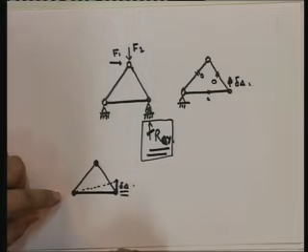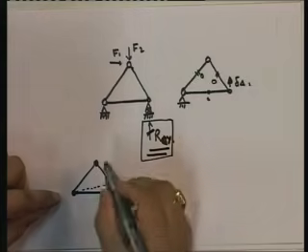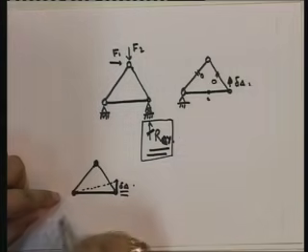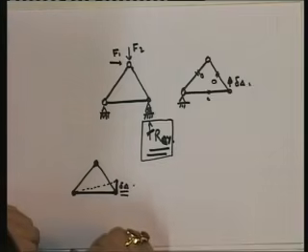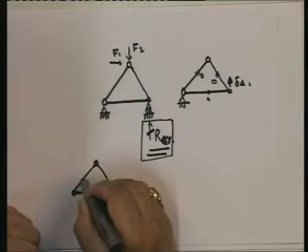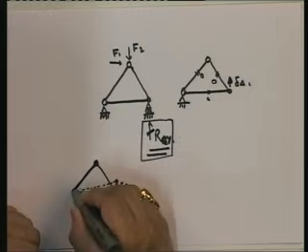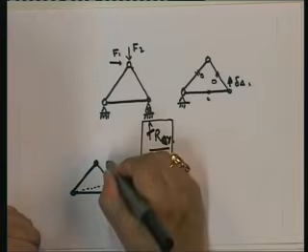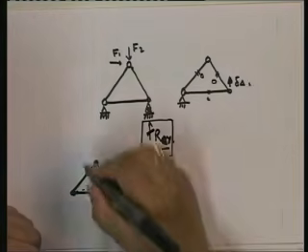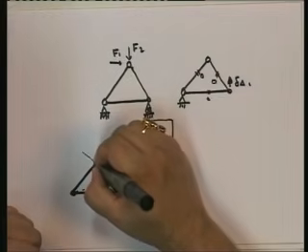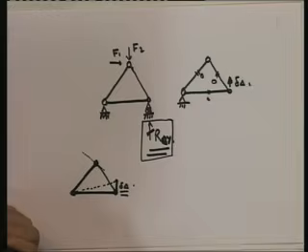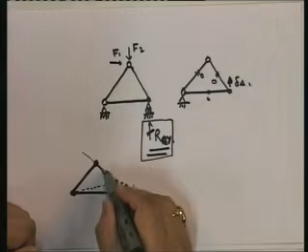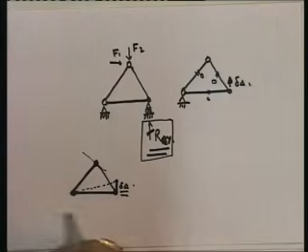So this one goes this way. Now I need to know where this point goes. So how do I do that? That's the geometry problem. What I need to do is understand that this member is connected over here, and since it cannot deform axially, the only way that it can move is along this direction. Now how do I get where it's gone? Has it come here? Has it gone there? That's what I need to find out.